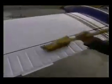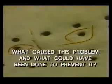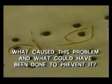External aircraft skin surfaces are readily visible, and maintenance and inspection procedures for them are well established. There are several problem areas that you must be able to recognize and treat right away to prevent the cancer-like spread of corrosion. The corrosion is easy to spot around the head of this rivet. But what caused this problem, and what could have been done to prevent it?